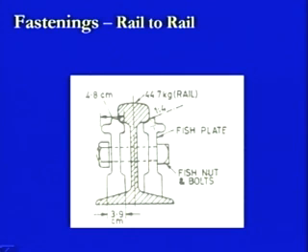Now, as soon as it gets fit in with this rail section here, we can assume that whatever load is coming from the top at this location will get distributed not only through the web section of this rail to the foot of the rail section, but will also get transferred through this section as well as through this section and will come back to the bottom.